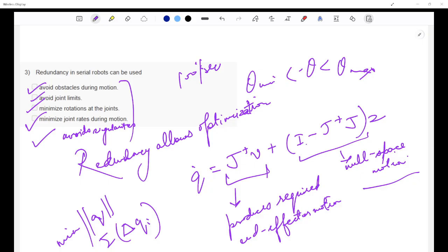So, even if there are so many advantages, the problems are that the control is complex, the computation may be expensive, would be expensive definitely, and then the inverse kinematics becomes even harder because you increase the number of motors. Okay, and it comes at a higher cost. So redundancy basically allows the optimization of robot motion without changing the end effector pose.